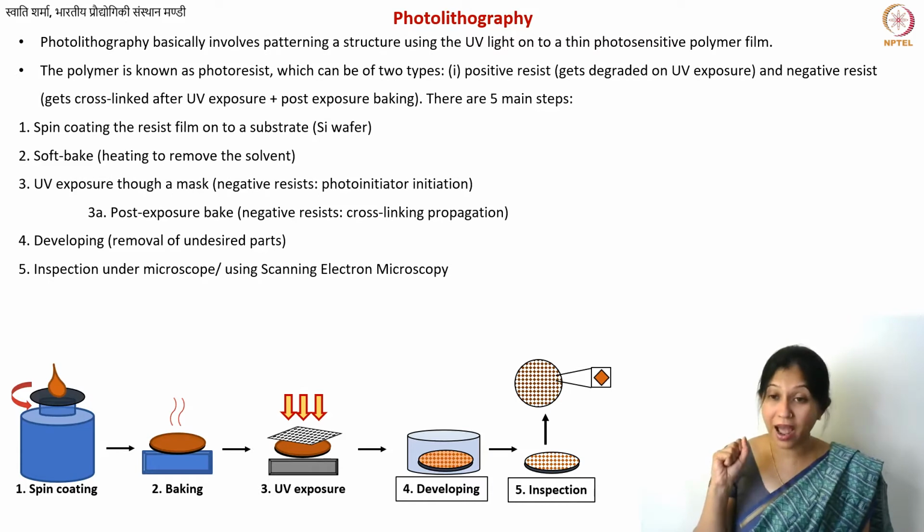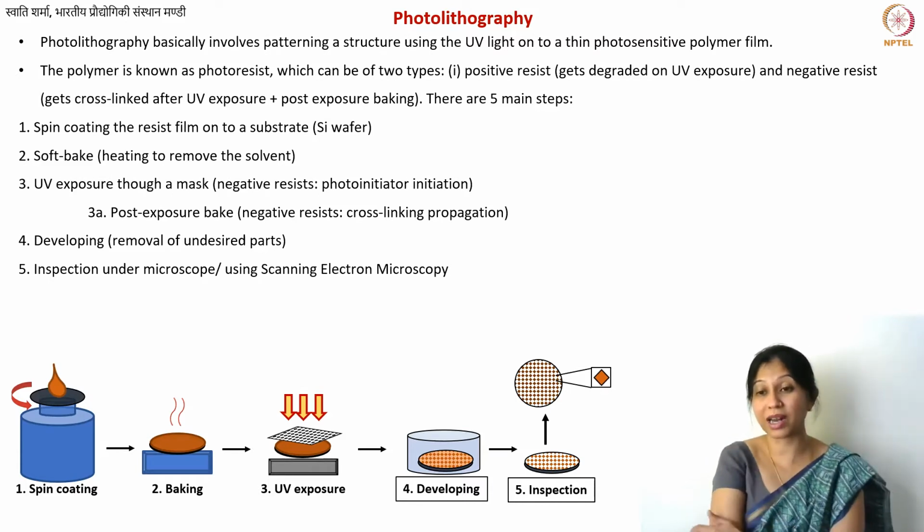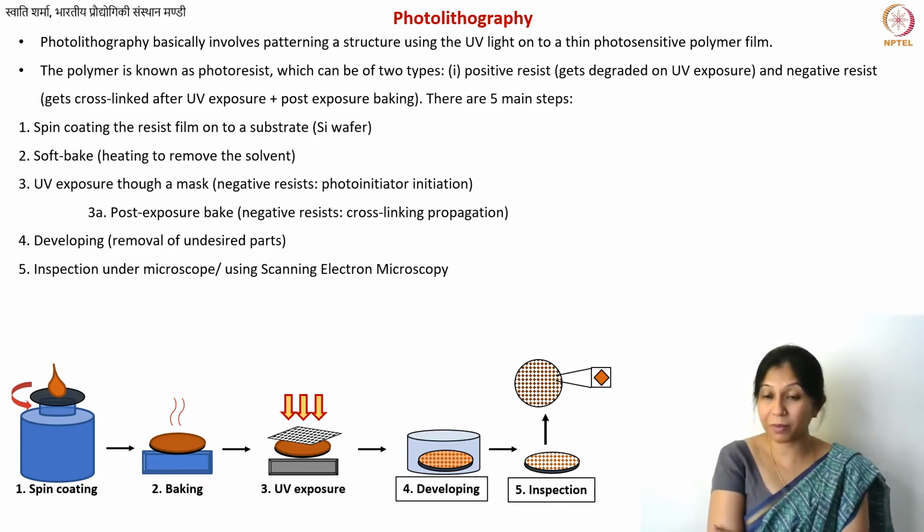Now, there have also been questions about whether or not this material should be called glassy carbon, because traditionally what is called glassy carbon is prepared at 3000 degrees, and many people still believe that it's not just about the removal of the impurities, it's also about the kinetics of carbonization and graphitization, which may not be possible at temperatures as low as 900.